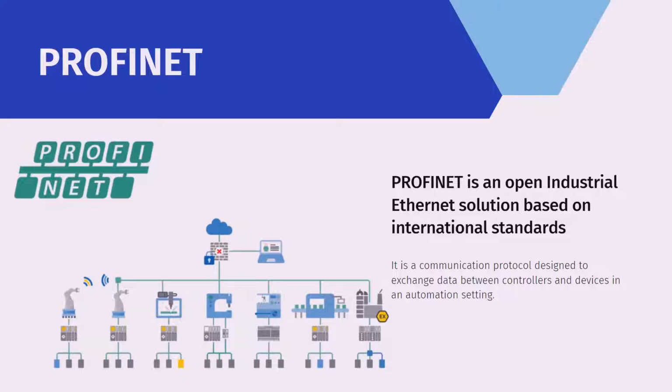To link all of those components, Profinet employs standard Ethernet for its communication medium. Ethernet cables connect Profinet components within a network, allowing other Ethernet protocols to coexist within the same infrastructure. Besides Profinet, you can employ other Ethernet-based protocols to complement the network, such as OPC-UA, SNMP, MQTT, or HTTP. With Profinet, standard communication and safety-related communications are both achieved by using a single cable that significantly reduces